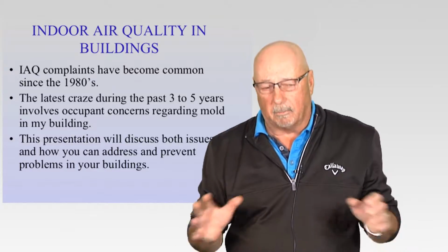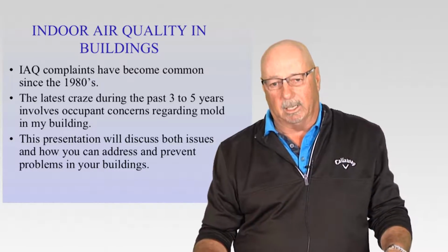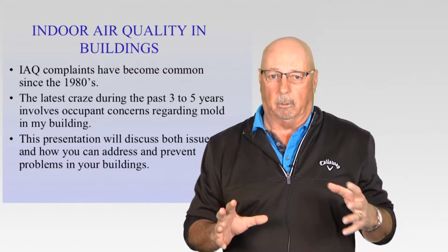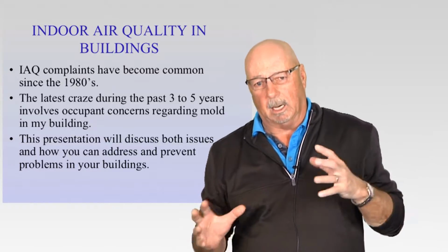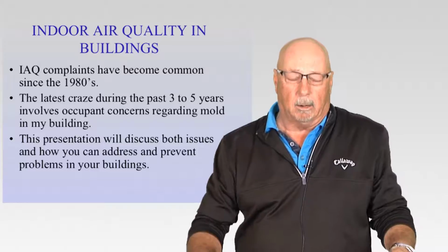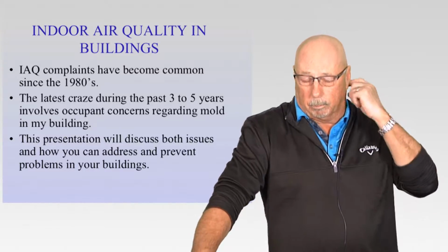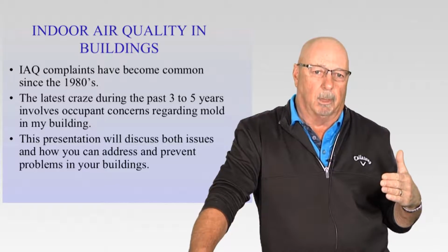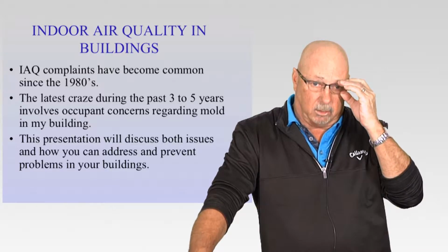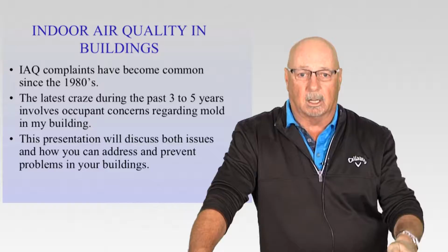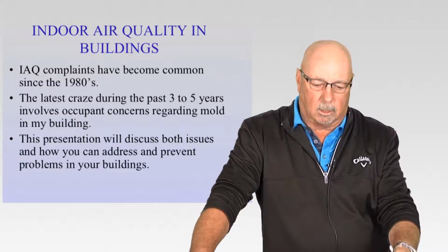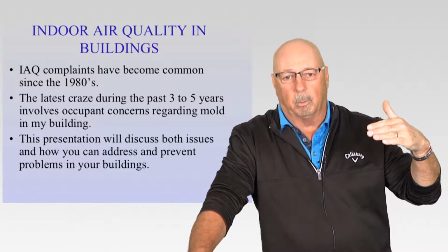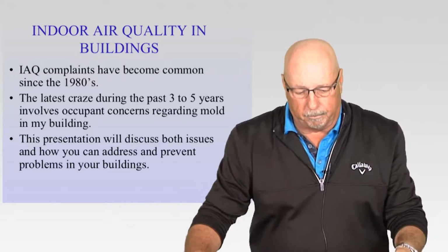And because they were designed that way, we basically built in indoor air quality problems, because we didn't have the means to bring in fresh air to replace or reduce some of the low-level contaminants that were being generated in these normal office-occupied buildings. As a result, those levels would build up to the point where it would create a problem.